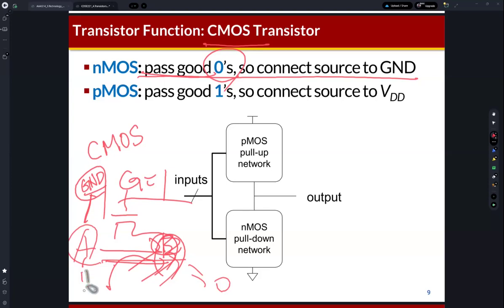However, if A is the high voltage, then B cannot become high voltage like VDD, clearly. For the NMOS transistor, this is the driver, so the data is given to node A and it drives. If A is 0, low voltage, then B becomes 0 clearly in the turn-on state. But if A is the high voltage, then B cannot become high voltage. So that's the problem. This is an analog property, an analog characteristic of the NMOS transistor.